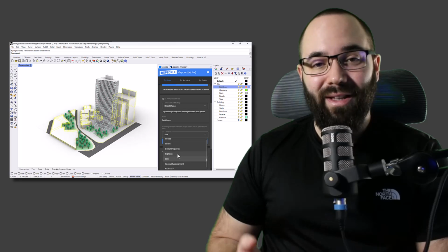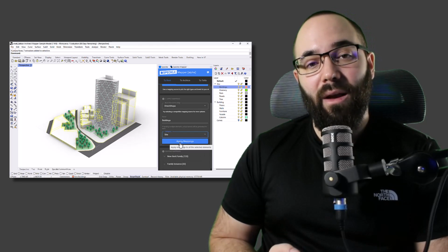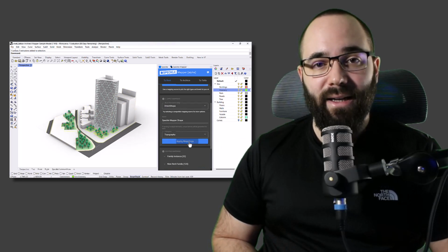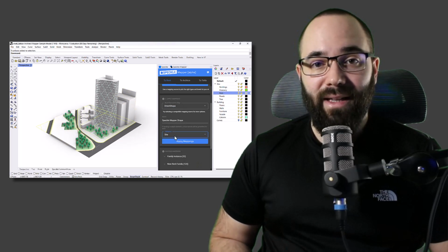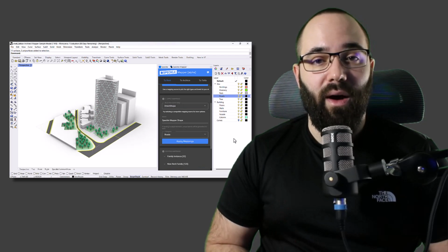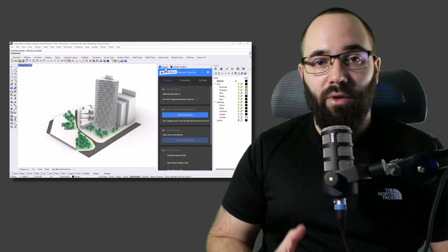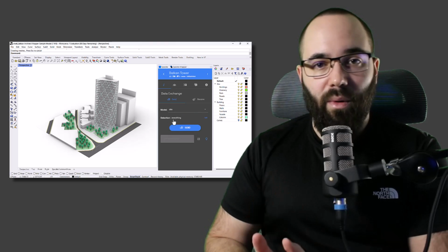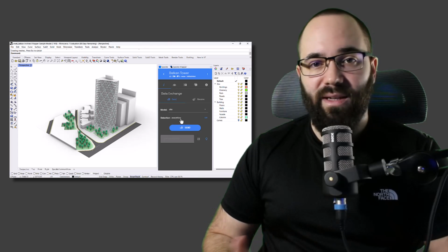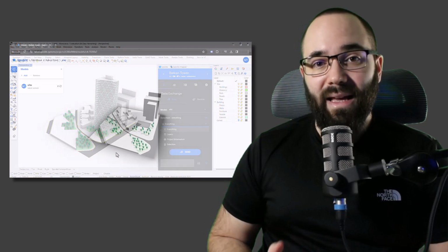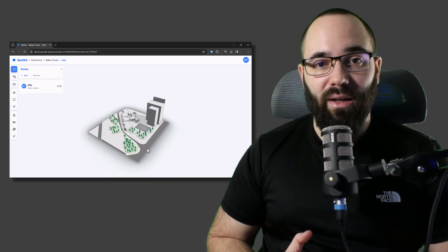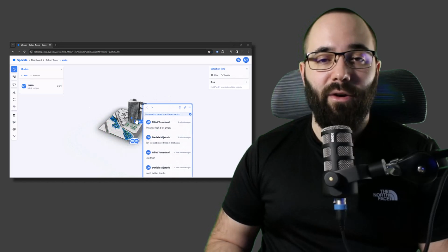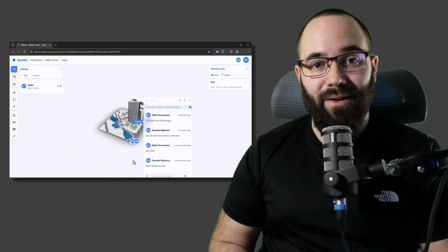And then you go to the Rhino connector and you pull in all of that Revit data, and you use the Speckle connector in order to assign which type of Revit family is going to work with which part of Rhino geometry. So you have a floor in Rhino, you assign a proper floor type from Revit. You have a wall, you assign a proper wall type. You have some additional families, you do the same. Then you publish that Rhino model to Speckle, and then you can use the viewer in order to communicate with other team members and work on the project there if necessary.